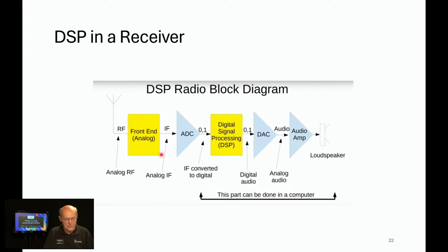So once we've gotten the signal down to a level that we can deal with, frequency-wise, then this is like one of the previous slides we showed, analog to digital. Then we do our digital signal processing, all of those wonderful functions that can be done, convert it back to analog, audio amp, and then we can hear it. So this can happen basically any place we've been talking receivers in the receive chain.